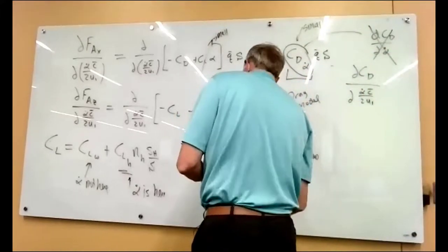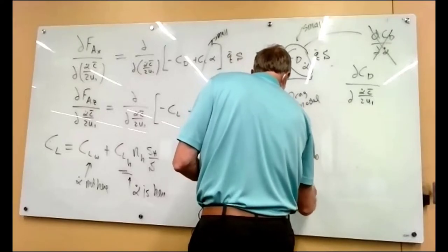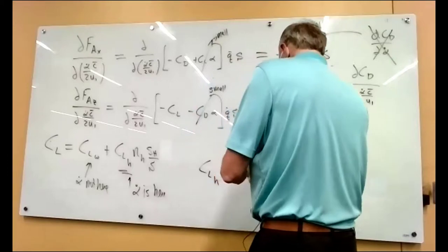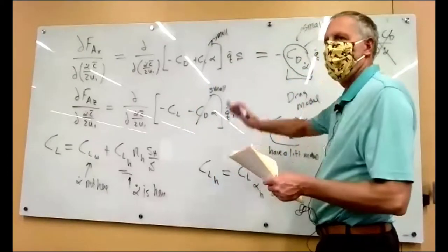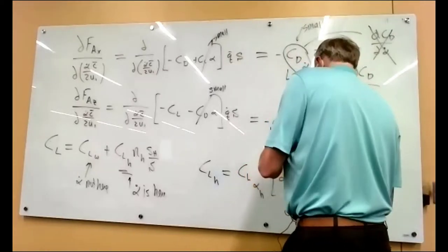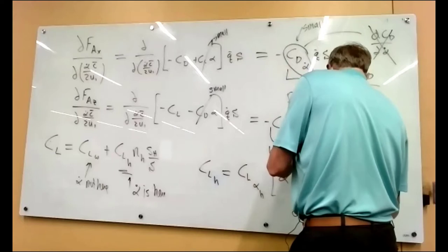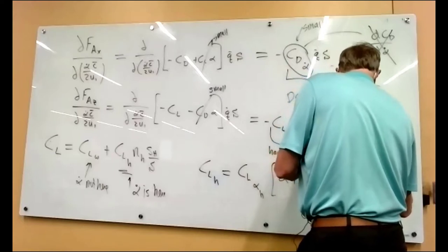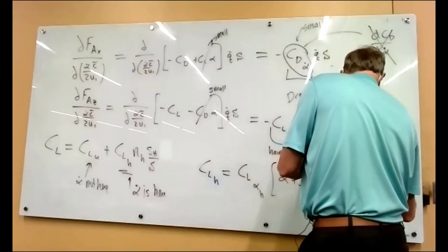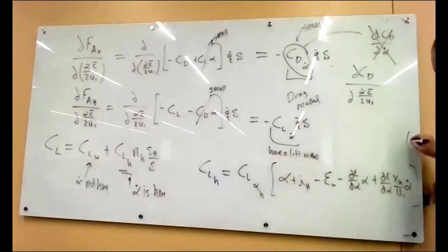And then we multiply it by the angle of attack, which is a big complicated thing because it's the angle of attack of the airplane plus however much we've tilted the horizontal tail up minus the downwash. And here's where we use our model. And then we go, aha, I knew alpha dot was in this somewhere. There it is, right there.